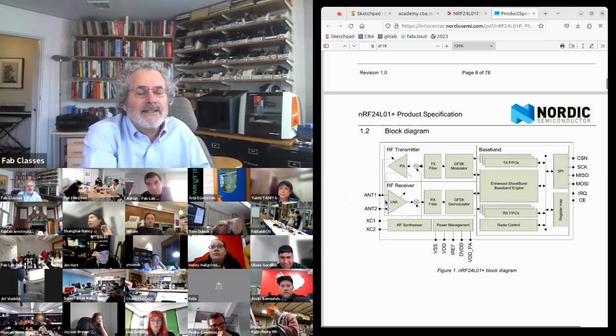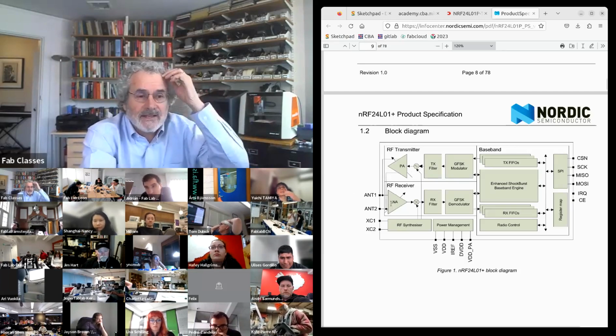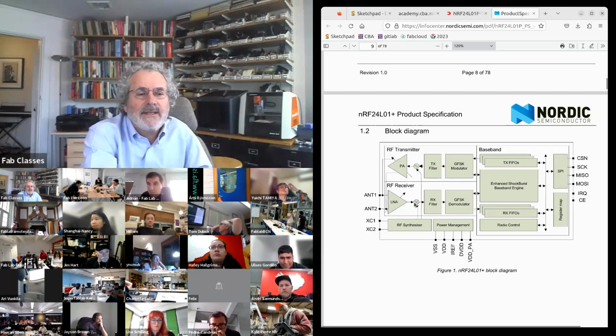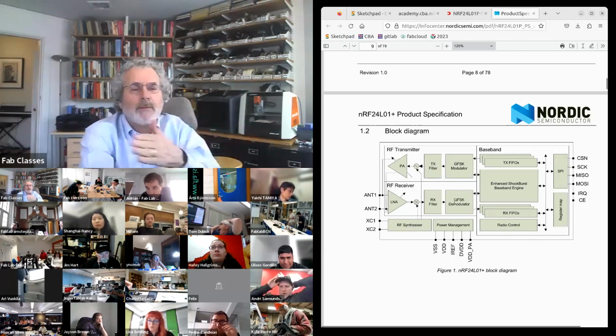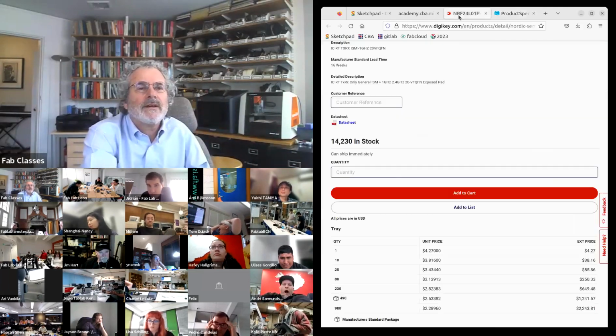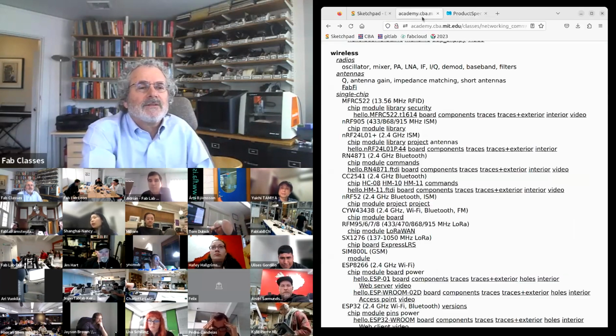Then there's a sensitive amplifier that reads. This is a high level signal. The receiver reads a low level signal. That's at the radio frequency. It then has to demodulate it back to a low frequency signal, chop it up, and give you the data. So those are all the parts of a radio.